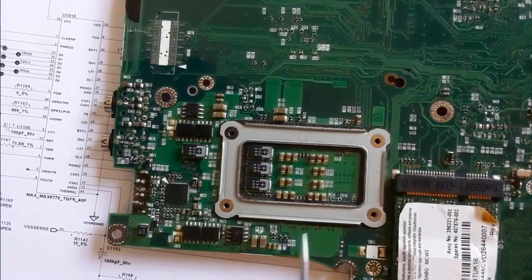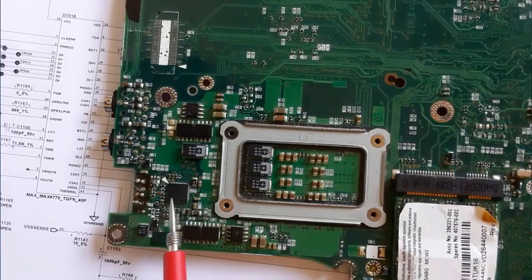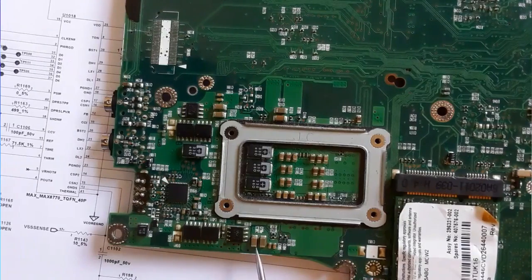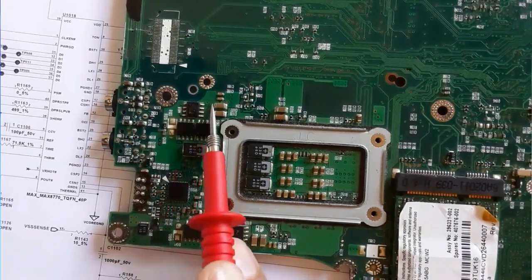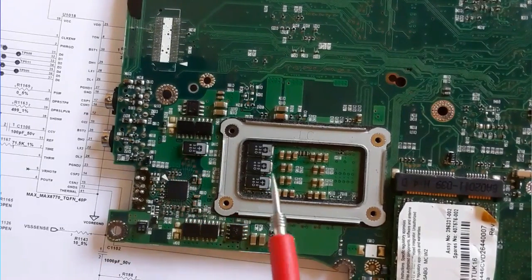Here in the motherboard, as you can see, we have many ceramic capacitors, so we have the IC that should be checked. We have here the ceramic capacitors around the IC. We have the MOSFET, which should be checked. Okay, the ceramic capacitors, as you can see, should be checked against the ground. Also here in the other channel, you should check the same components.